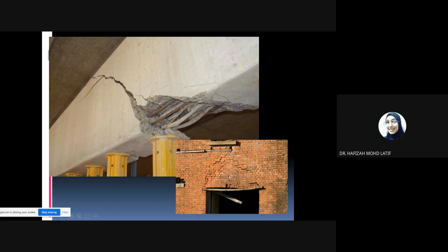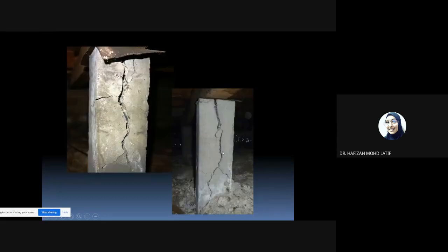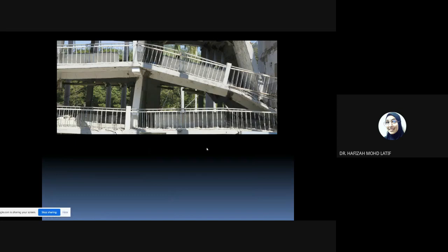This is a load bearing wall. The same failure here. Okay, this is a column crack, dangerous. So they have to underpin. They have to support the building first, by using shoring or relevant support like hydraulic jacks, and they have to redo this again. This is the consequence when they have structural defects.